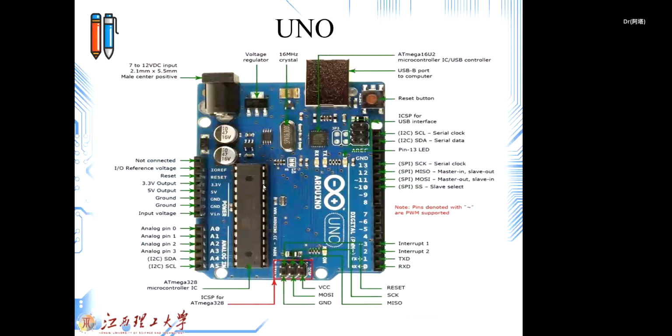Okay, but our target in this lecture is the Uno. And now this is the better hardware description regarding the Uno microcontroller, or Uno Arduino. You will see here the analog pins and some words like SCL and SDA that I already talked about regarding the I2C communication protocol. These two pins can act as SCL and SDA. You will see the words TX and RX, which are for the serial communication.